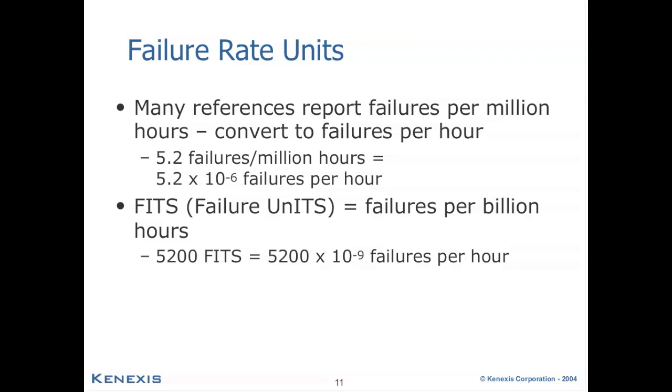We may also choose to refer to these in terms of failures per billion hours, and this is typically known as FITs, short for failure units. So using the previous example, we would define this as 5,200 failures times 10 to the minus 9, or 5,200 FITs.